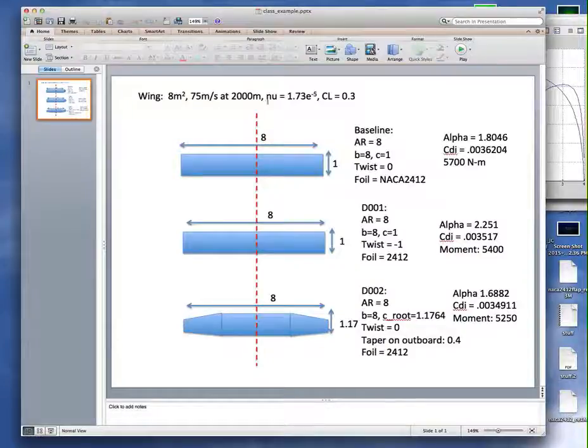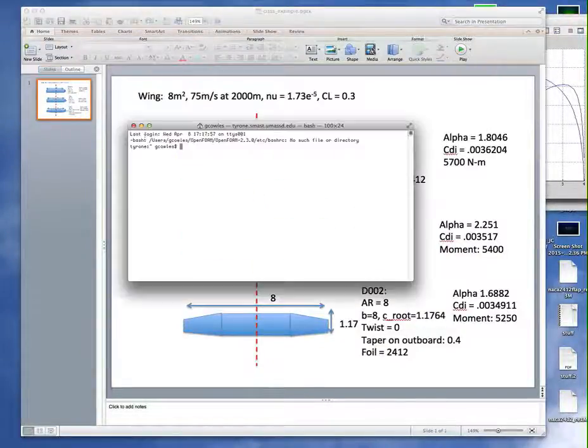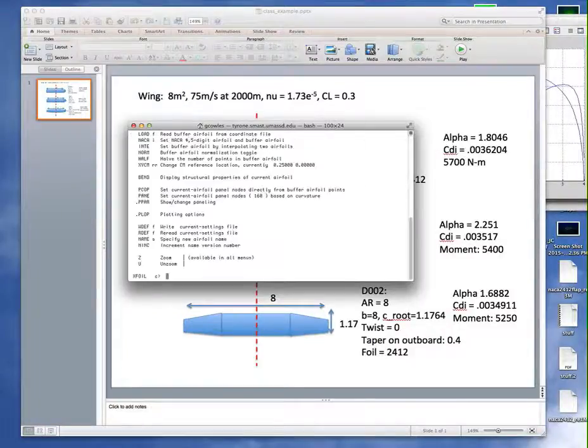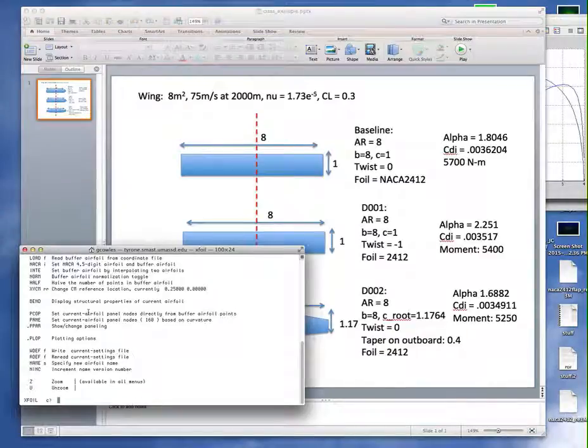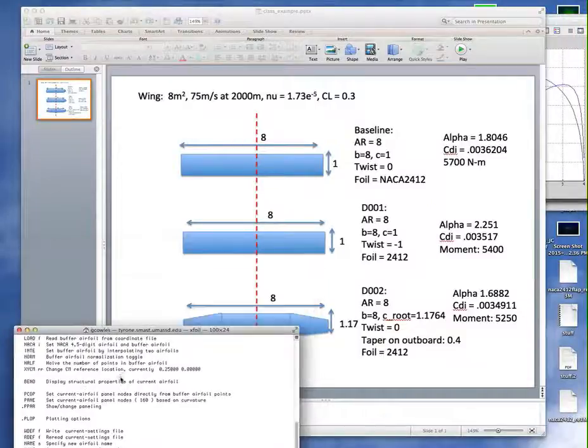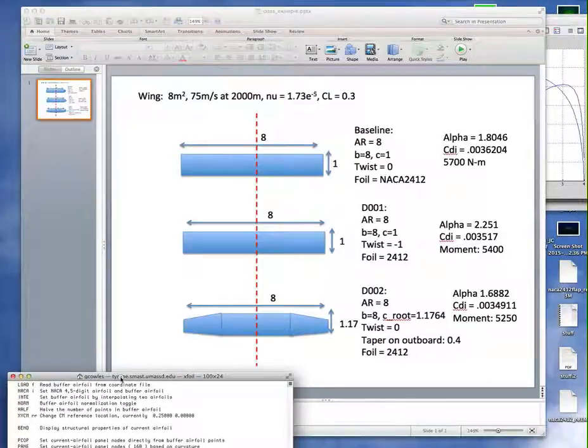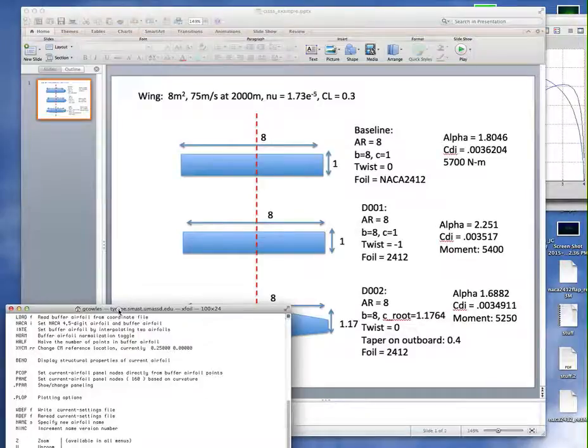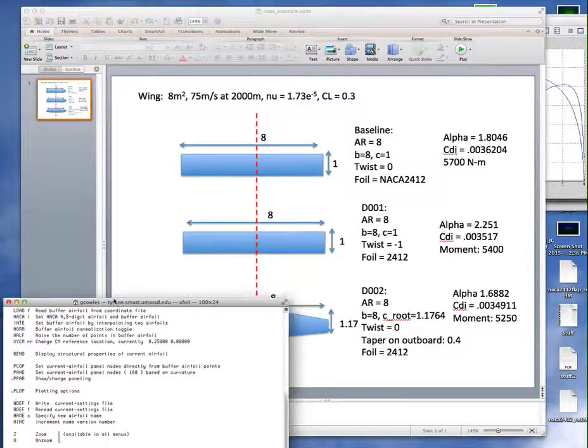I think I've got to keep this open. Xfoil. Let me grab my terminal. All right. So if I start Xfoil, I put the run commands that you really need in your project file. They're pretty quick. So we're going to do NACA 2412. What I want to know is, estimate the profile drag on the structure.